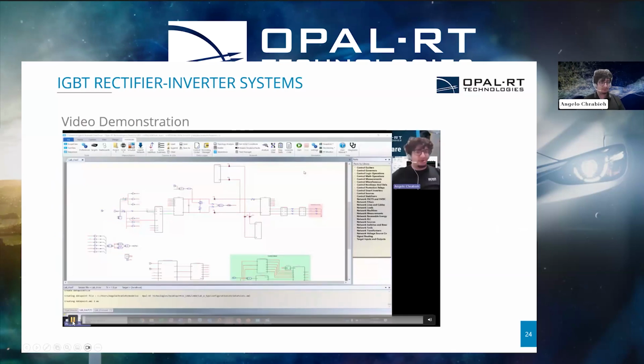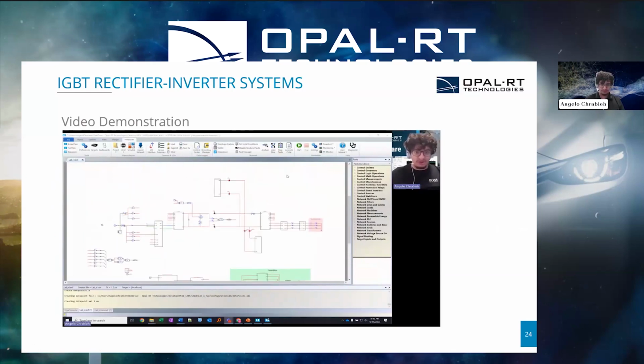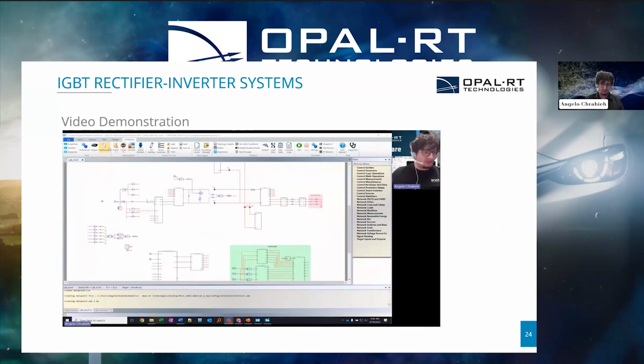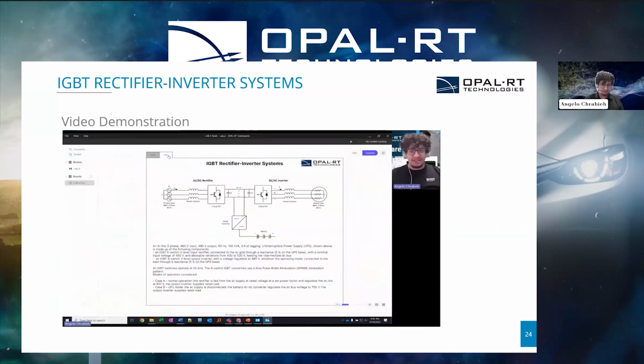Hello, my name is Angelo. In this video, I'll be showing you how to use the IGBT rectifier inverter systems in HYPERSIM. As you can see, this is the circuit that we are working on. You can start by clicking on dashboards and going to help. The IGBT rectifier inverter systems have been implemented in this case to be used with a UPS system.